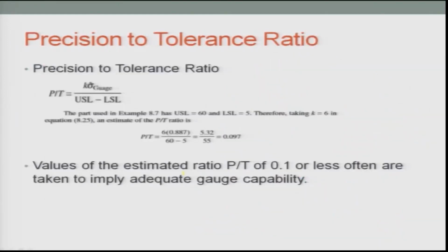So, now I want to find out the precision to tolerance ratio. If you remember, I did mention time and again, it was basically two sided or one sided. For the two sided one, I found the difference between the upper control minus the lower control and divided by 6 sigma, depending on the level of confidence which is there, and the coefficient being 3 because you want to cover about 99% of the area would be the 6 sigma concept. The coefficient would be 2 depending on the overall coverage being 95% of the area, and similarly you can do the calculations accordingly.